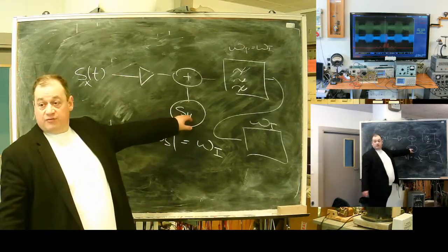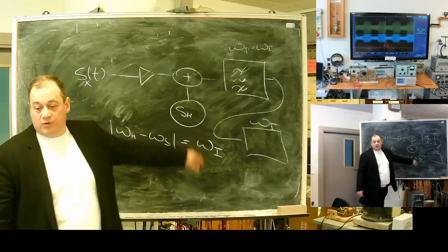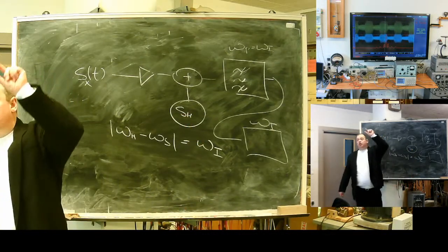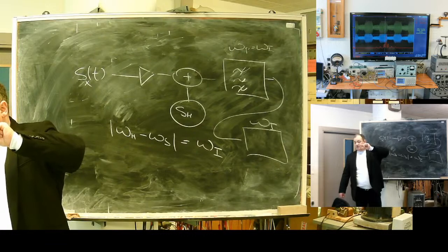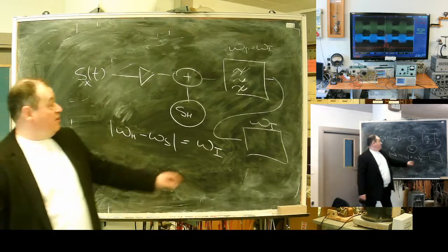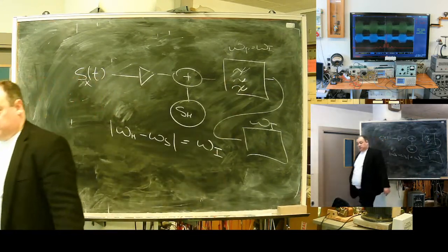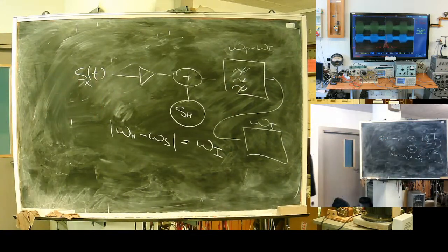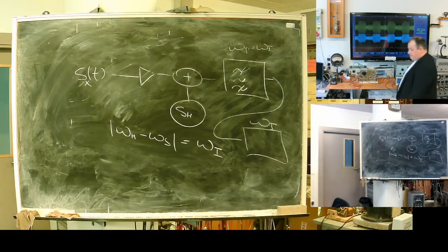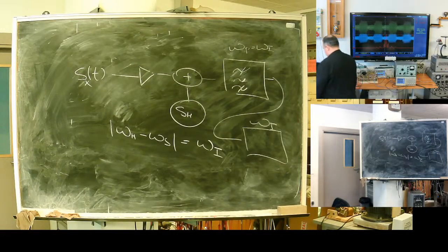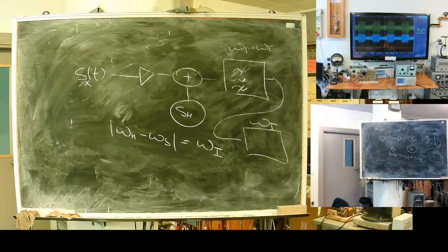Change the frequency of the heterodyne, and you will cut from all possible frequencies one slice with the width of your filter. Use a band generator. This is the idea of spectrum transfer.